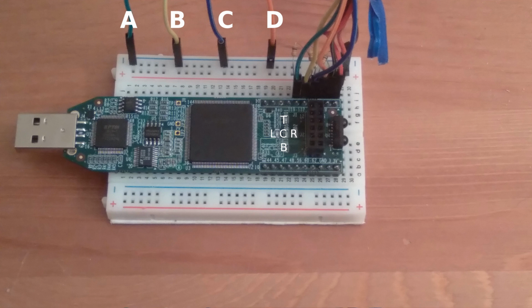This first demonstration won't do anything particularly remarkable. This will just show simple asynchronous and synchronous logic and how to use make, Icarus, and GTKWave. For this, we will need a Verilog source file, a pin constraints file, and a make file. First, we'll look at the Verilog source file, called basic.v.